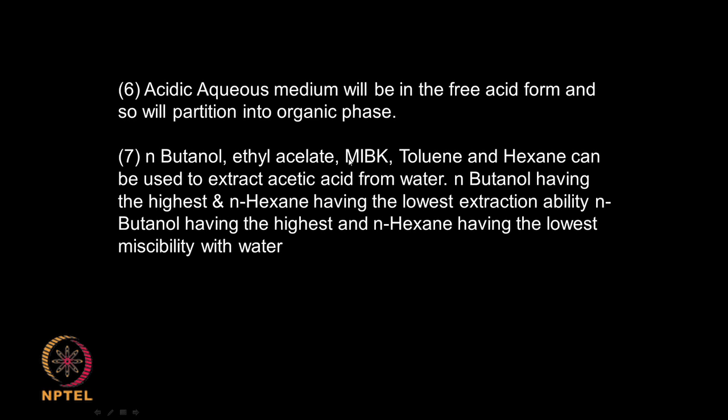So there are certain conditions: whether it is a free base, whether it is acidic, whether it is a salt, whether it is a polar compound or a non-polar compound. We can select solvents based on these conditions as well, so that the separation is efficient and the miscibility between the raffinate and the solvent is minimal.